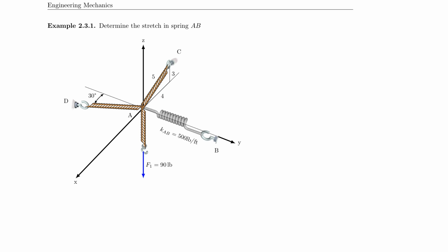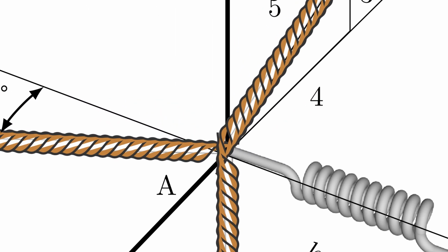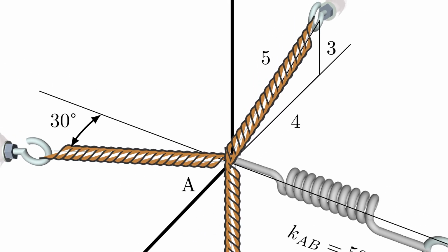And maybe the first thing I'm going to do is actually superimpose a little free body diagram. And since I can zoom in here and make sure that we understand that it's really acting at this node, I'm going to draw the free body diagram for node A here. And what I will find is that I have forces in all 3 directions, but differently distributed over the cables.